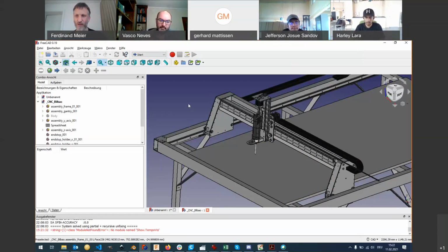You can do all those dirty tricks where you copy one file, rename it, and use it for something else. FreeCAD doesn't care. It doesn't require any internal IDs and stuff like Fusion does. As long as it's a file and it has the right name, it will fit into your FreeCAD assembly. And if the surfaces still have the same name, you won't even have to reassemble it.